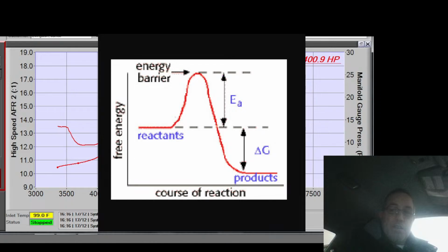Well, they are really, really quick to burn, share energy, and go through the cylinder. So we get a burn speed of 20-something meters per second versus like 18 or whatever it is for gasoline, right? You get a much faster burn speed with the higher density, oxygen-carrying fuel packed in the cylinder than you would with something that was lower density, spread out more, and doesn't have oxygen.